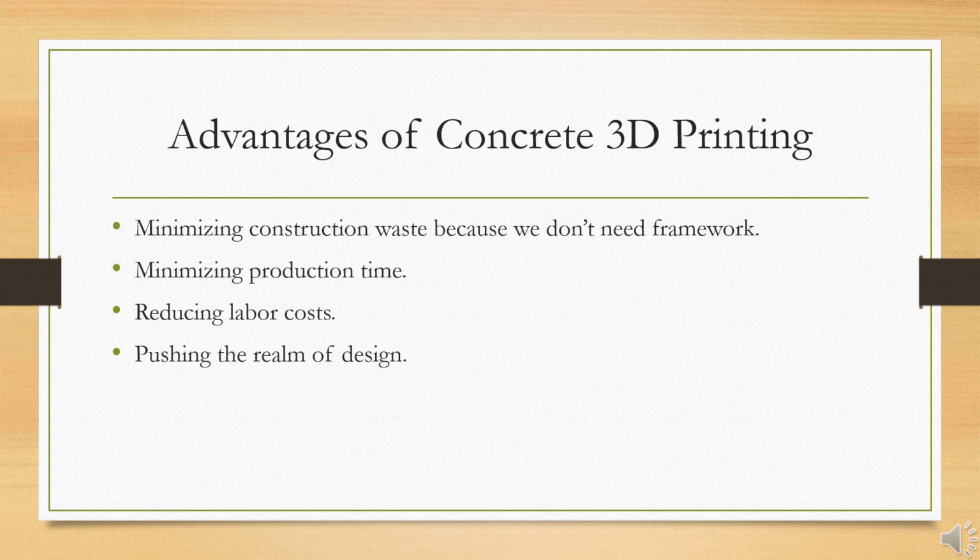Now, there are many advantages in concrete 3D printing that keep scientists and researchers holding on to this field and really pursuing it and advancing it. The first one being minimizing construction waste, because we don't need any framework, as the 3D printed model is not put into any mold. It is printed directly, layer by layer over the other.